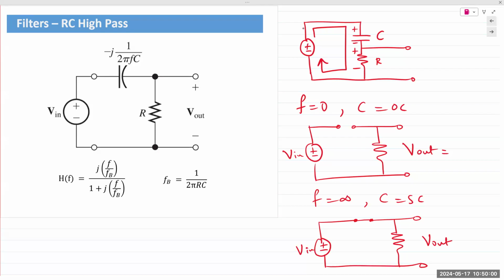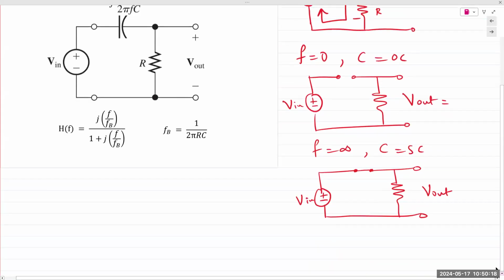You're overthinking this. Output is yes. It's a short circuit. You're simply connecting the output directly across that voltage supply. Taking the output across the resistor means taking the output across that voltage V in. So yes, we do obtain an output.